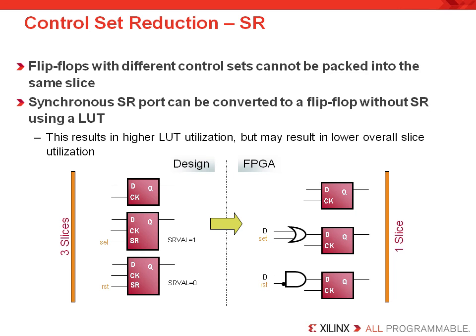This slide demonstrates how the implementation tools benefit from the use of synchronous set and reset signals. In this case, these flip-flops can be placed in the same slice, since the set and reset inferred by your HDL code is synchronous. The implementation tools just migrate the set and reset to LUT inputs rather than mapping them directly to the register ports.